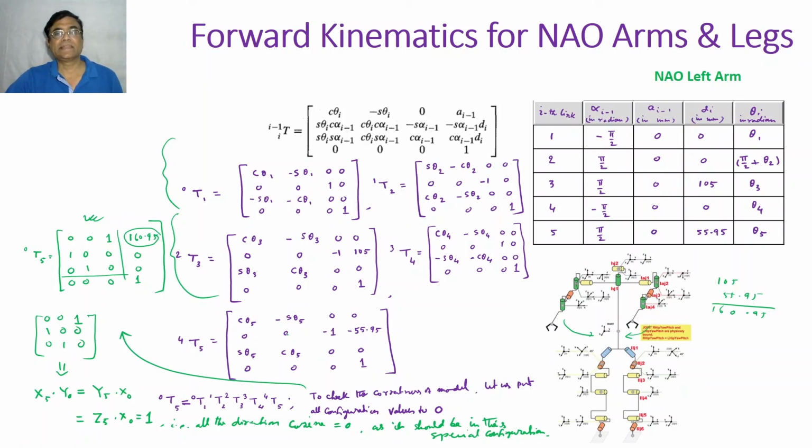Once it is written correctly, then with this forward kinematics of the arm, you can, using Choregraphe software, move the arm the way you want, running several loops. All the angle ranges are given. Run the loop within that range, and you can move using forward kinematics.